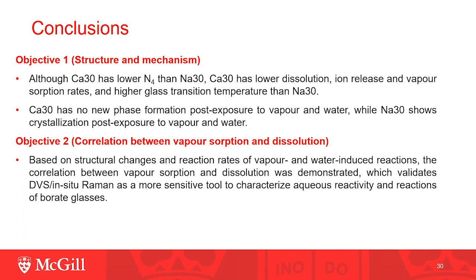Thirdly, based on the structure change and reaction rate of vapor and water-induced reaction, the correlation between vapor sorption and dissolution was demonstrated, which validates DVS and in-situ Raman as more sensitive tools to characterize aqueous reactivity and the reactions of borate glasses.